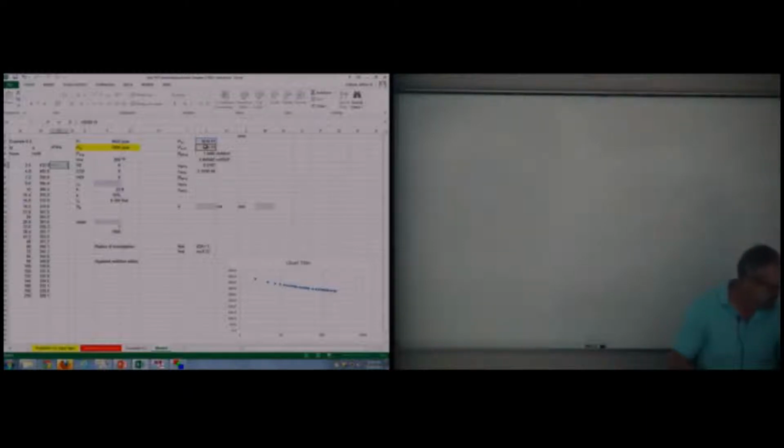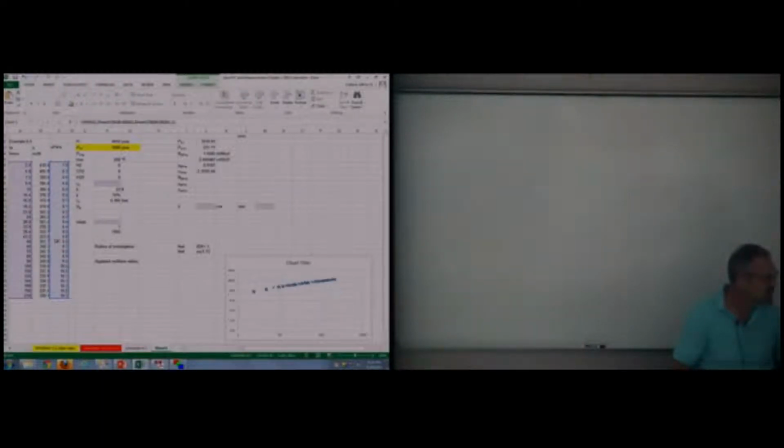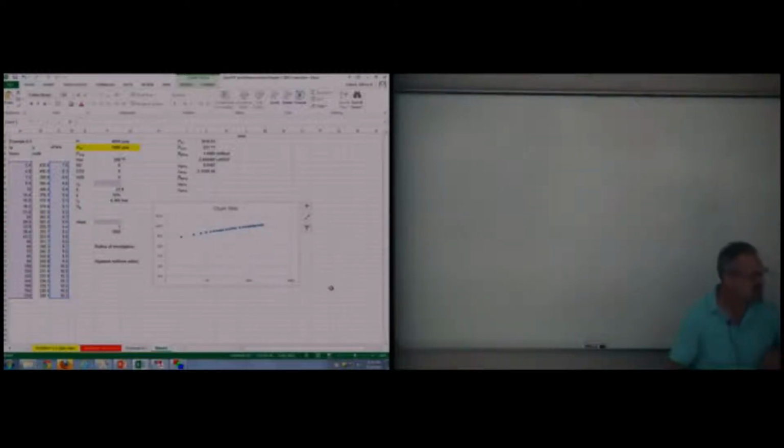I would normally not do this because it's a constant, and I'd plot the raw data. But that constant divided by Q is reciprocal rate. And that's what we're plotting, not rate, reciprocal rate. Then that should look like the textbook plot, and that's what we're going to get our slope and intercept from. So each one of our rate points is reciprocated and multiplied by the apparent pressures at initial and flowing conditions. I haven't calculated anything yet except for that column. All the data was given.